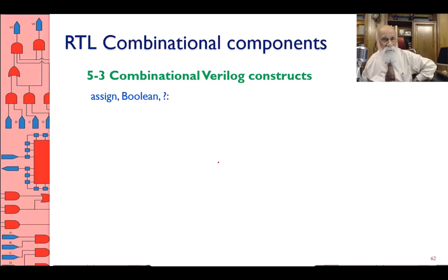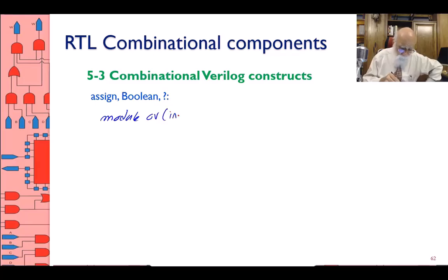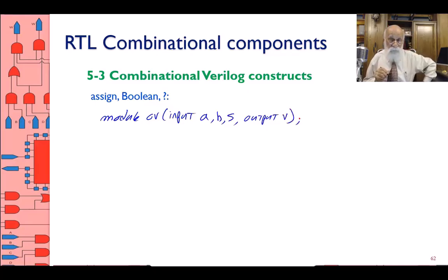Okay, I can have a module, how about overflow circuit, input A, B, S, these are single bit, output V, which is the overflow. This module, I can write an assign statement, a Boolean expression.